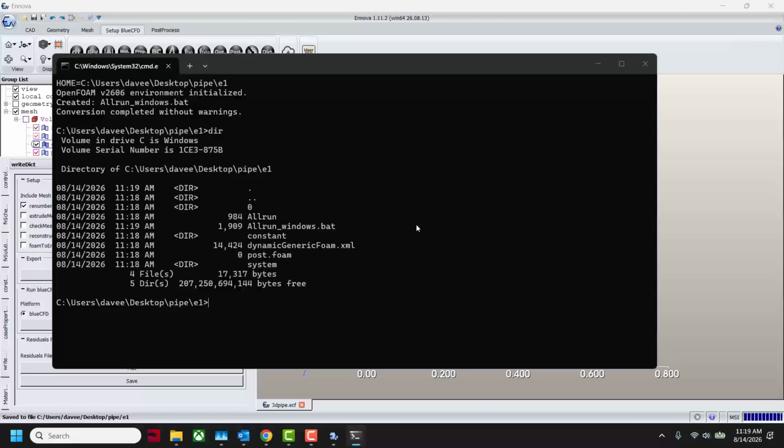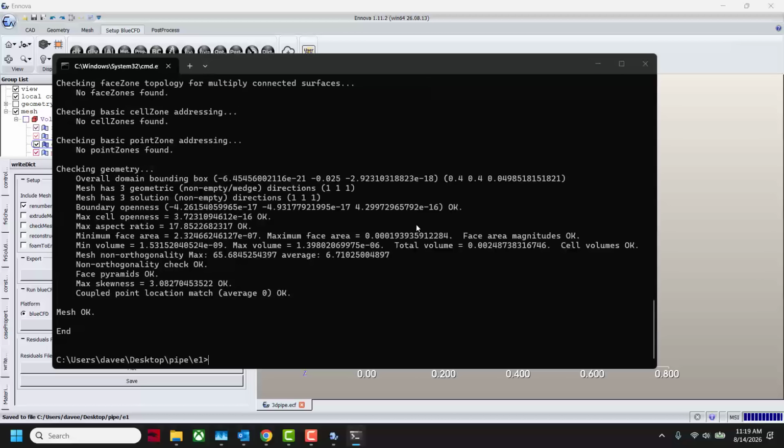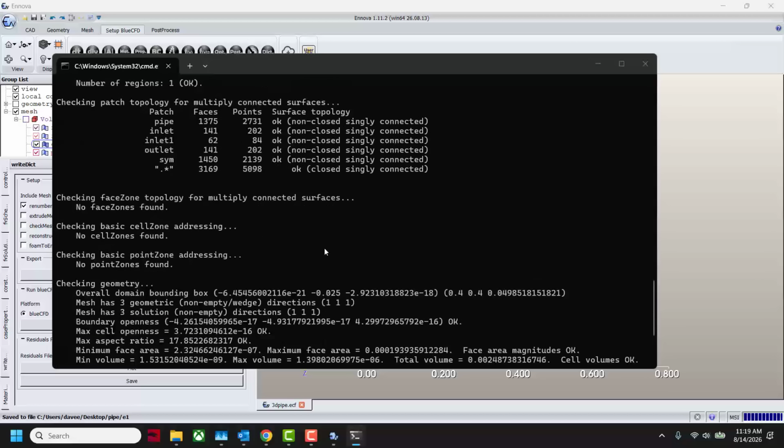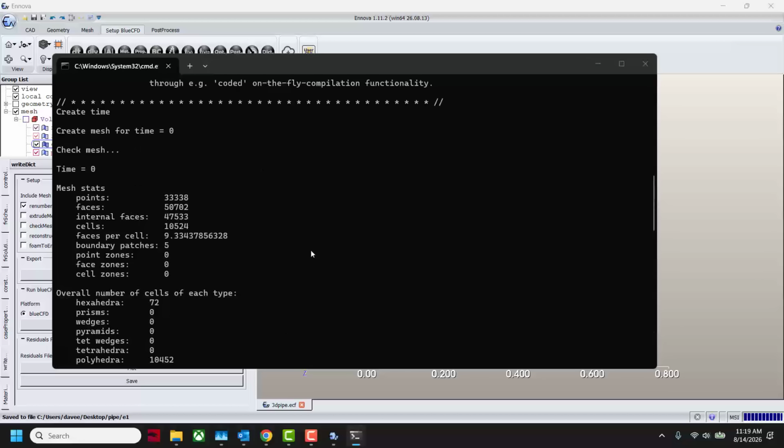So if you're doing rotating systems, ball bearings, turbine blades, anything that's moving mesh or overset, sometimes there's a very detailed set of procedures that you need to follow with different executables. Something simple we can do is just run OpenFOAM checkMesh, and you can see we've set up the environment. So this is the OpenFOAM program that's run. I just ran it from Windows, as simple as that.